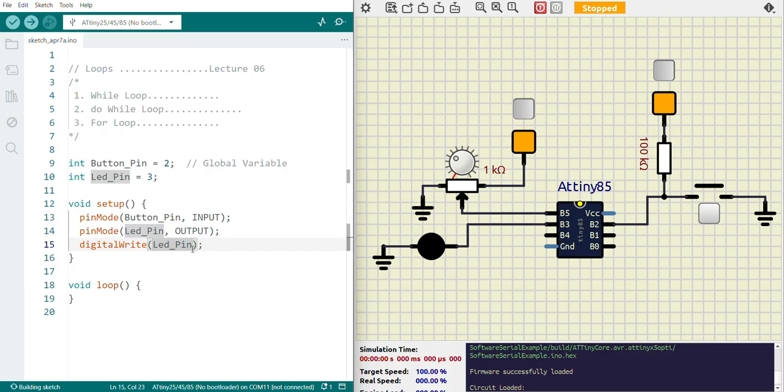All right. So I'm saying digital write LED pin low. You get the point? I want to start when it is off. That means, remember, the low gives a voltage here that is close to 0 to 0.8. So there isn't enough voltage drop across the LED to turn on, right? All right. So now that is what we have.